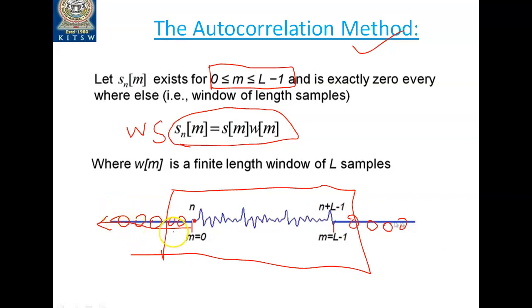If you draw the graph of the error sequence, a large error is possible here. The point is very clear: the basic idea of LPC is to estimate the current sample with the help of the previous past samples, but in this case the previous past samples are all zeros, so to estimate the current sample we will have large errors.